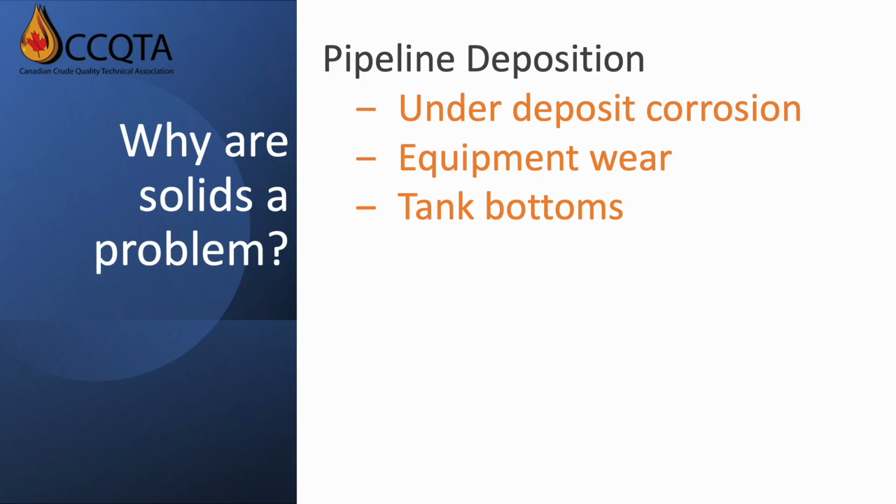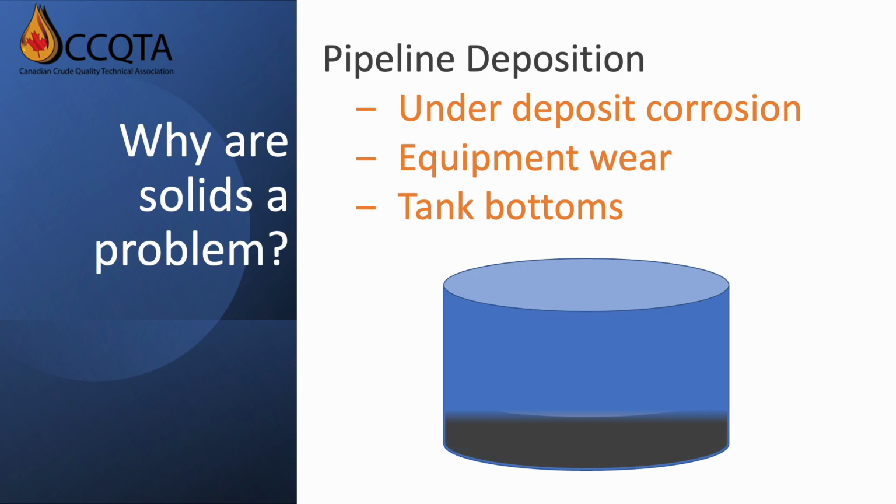Next, crudes that pass through intermediate or long-term storage tanks will deposit solids in that tank through settling. Over time, these solids build up, and eventually those tanks will need to be taken out of service for cleaning. Typically, tanks have a 20-year inspection and cleaning cycle, so excess solids can result in tanks being taken out of service way early, which is very disruptive and very costly.